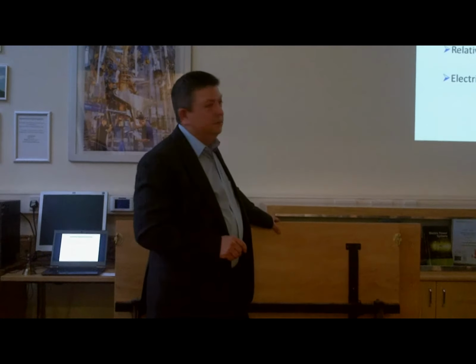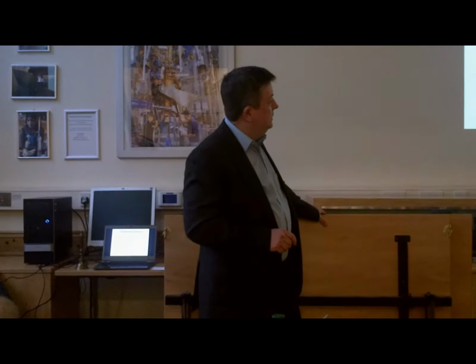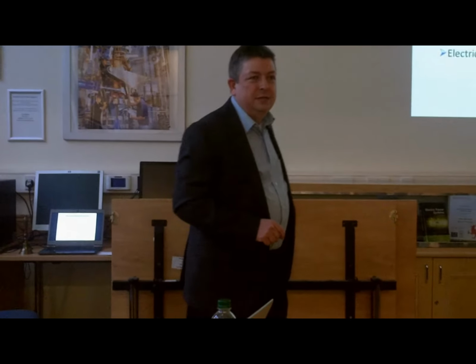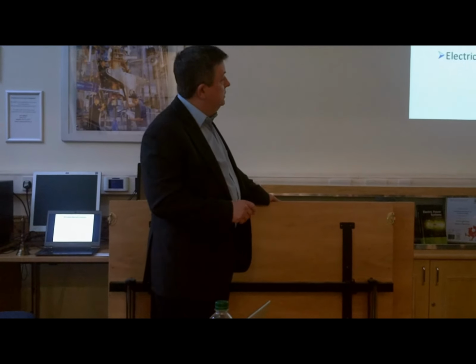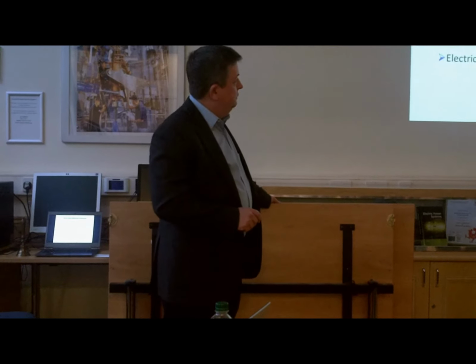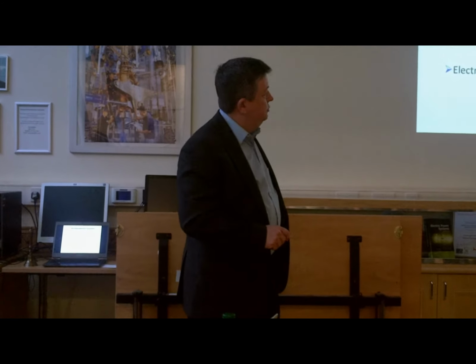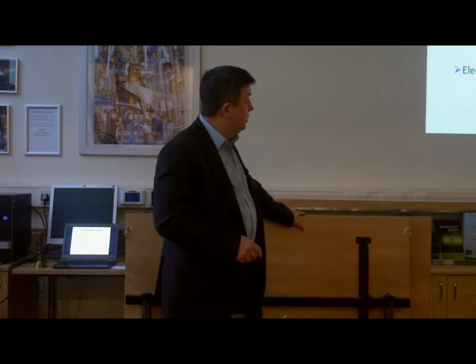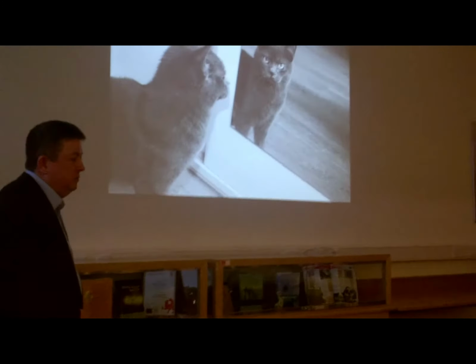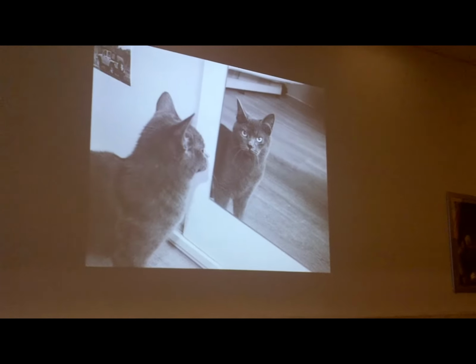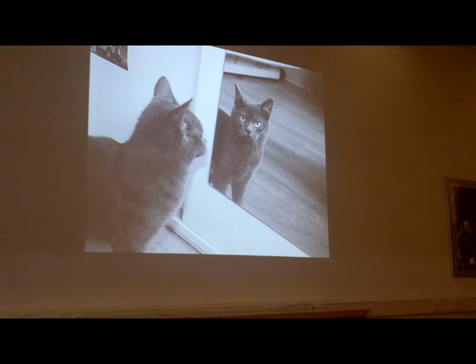I notice conductivity here I've written as a complex quantity because I've spent a lot of time looking at superconductors, and superconductors have a complex conductivity, or an imaginary conductivity, which makes them tick actually. So we're interested in measuring all those parameters as functions of frequency in the microwave spectrum, and also as functions of temperature. And microwaves, in common with all electromagnetic waves, of course, bounce off things when there's a mismatch in wave impedance.